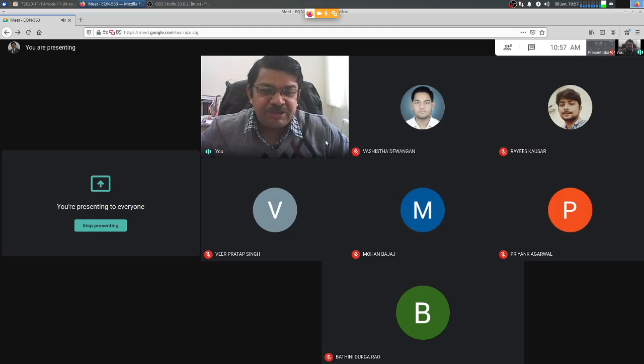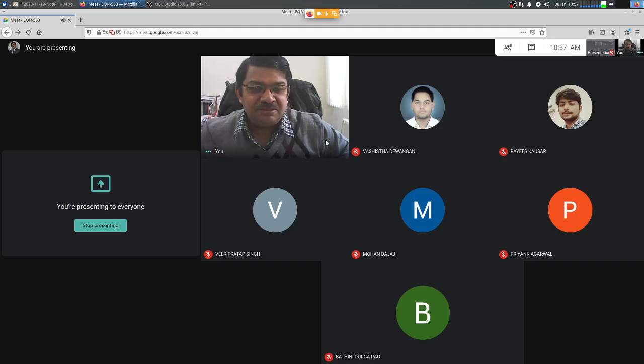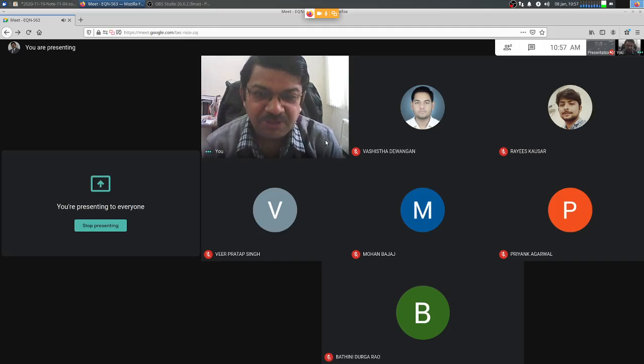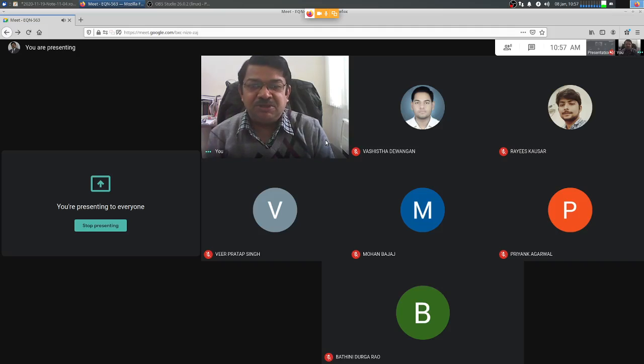This moment pattern is only because of the earthquake. In gravity load this moment pattern doesn't come at all, right? So in gravity load you don't have this issue at all. It's only under the lateral load that you have this issue that the sign of moment is different on the two opposite faces of the column.